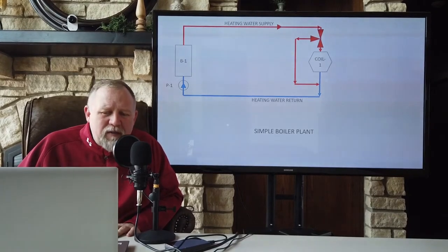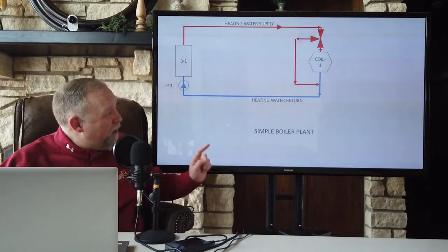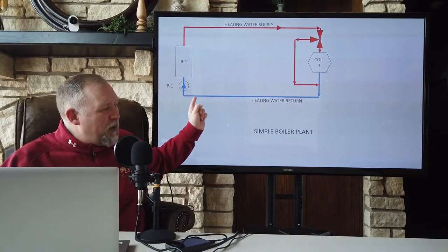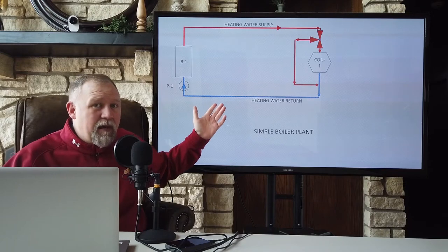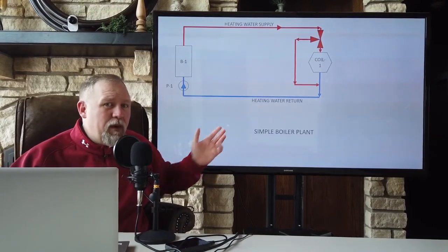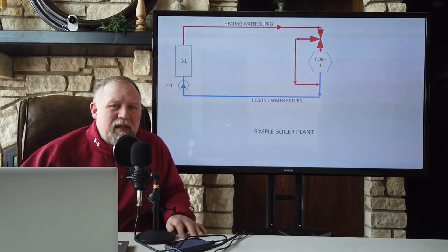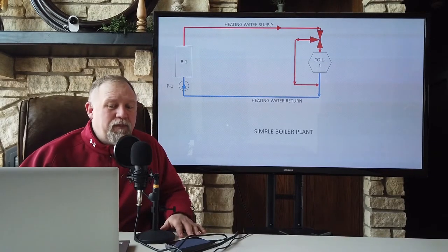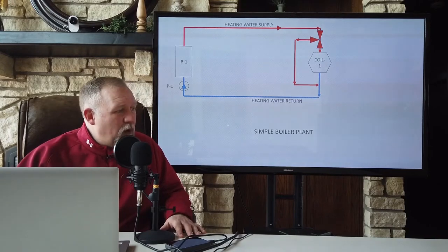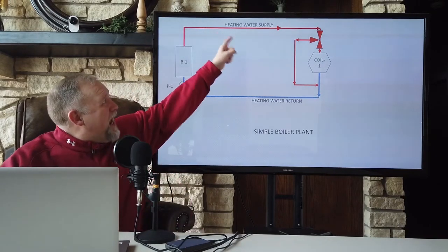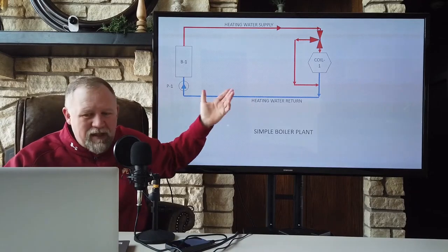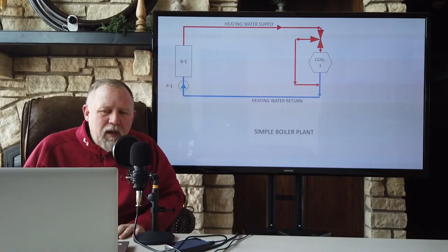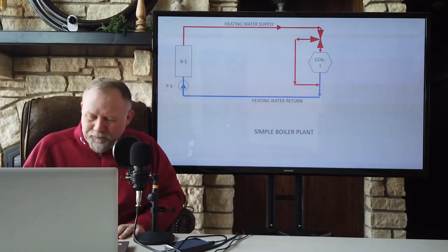Boiler efficiency varies with return water temperature. However, don't supply really cool return water to a boiler if it can't handle condensing. In other words, if the interior of that boiler isn't made out of stainless steel and it isn't meant to see condensing, don't do it. If you go into a lot of buildings, a lot of older boilers will use something like 180 supply and 160 return. That's fairly common, and that's what I've used for my examples today.